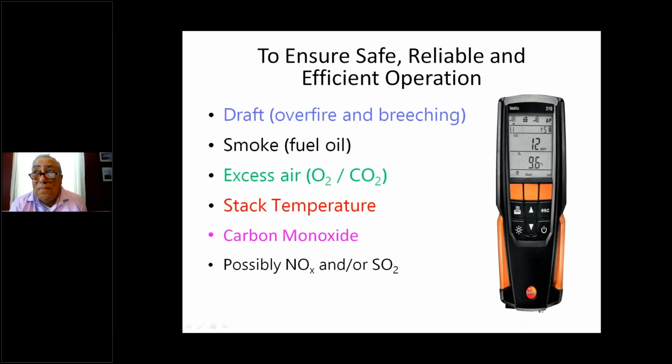Couple of other questions regarding excess air. One is a recommended excess air percentage, and what's the optimal excess air percentage. And is there a minimum stack temperature for oil? Those are three questions, but two of them are the same. You should try for 7 to 9% O2. If you see higher than 9%, and you start getting into double digits, that's excess air. That's too much. You really want to shoot for 7 to 9% O2.